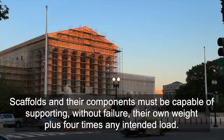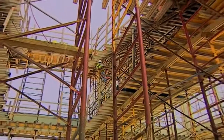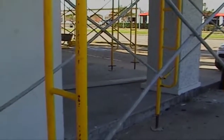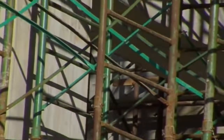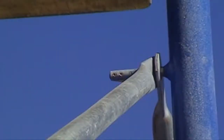Scaffolds and their components must be capable of supporting, without failure, their own weight and at least 4 times their maximum intended load. Never alter a scaffold unless it is done under the approval and direction of a competent person. Frames and panels must be connected by cross, horizontal, or diagonal braces. When frames are stacked, cross braces must be of sufficient length as to keep the scaffold plumb, level, and square. All brace connections must be secured to prevent dislodging.